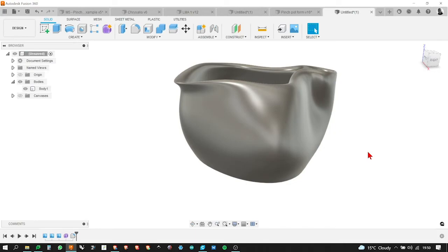Yeah, so in this sculpt, it's Alt, W, E, and R to change between transform, scale, and rotate. Right. So you could remap that to just W, E, and R. There are macros you can put into Fusion. I've never done it, but there are ways of doing that, certainly. You can also, if you're using one of these space mice, program those to do exactly that kind of thing. You can write your own macros for space mice, which is another really nice thing. You just press a button and it will do it straight in. I have done that in the past when I've been working commercially, but not anymore.